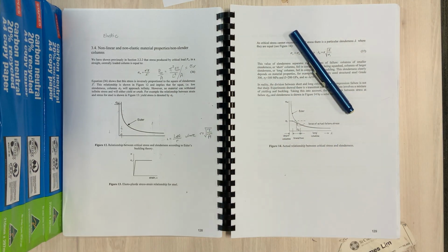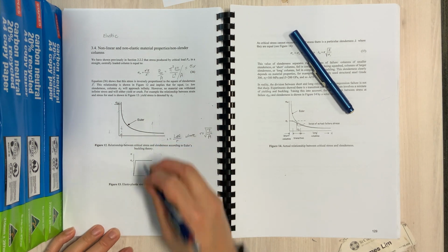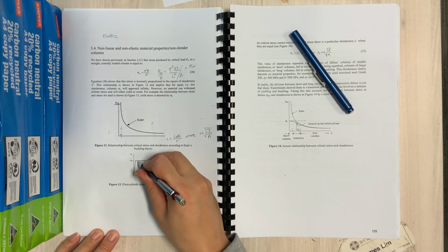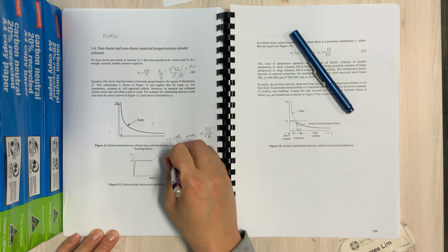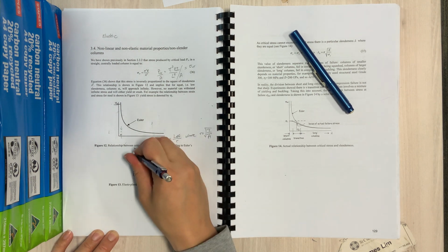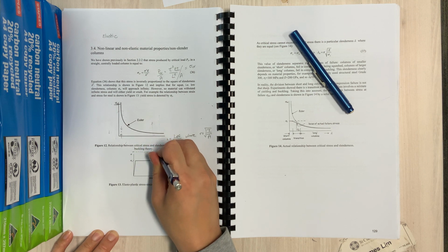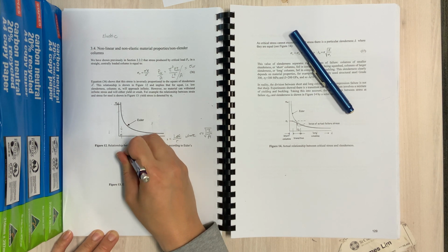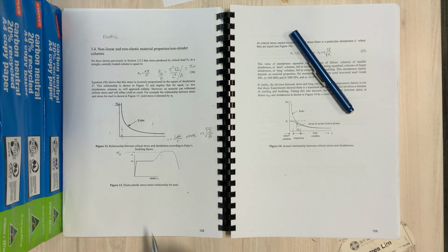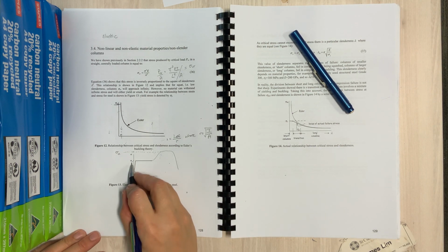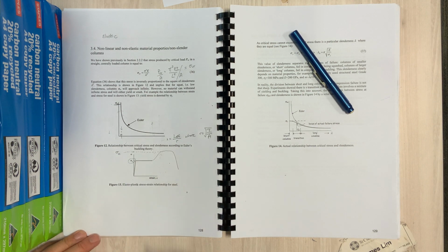I've just shown the graph of stress against strain for the coupon test. This is how steel behaves. There's a plateau, and then after the plateau it goes up, and then it fails there. That one there is called the yield stress, and this one is called the ultimate stress, or something to that effect. So Y is yield and U is the ultimate. And as we can see, when it comes to buckling, we're only concerned with the yield stress.